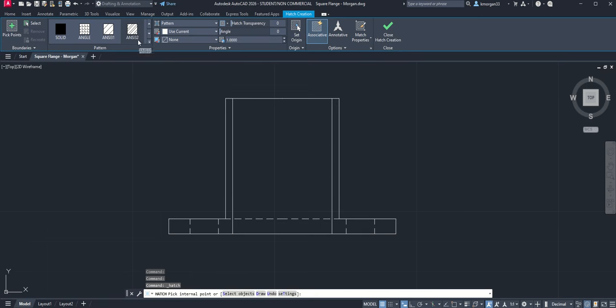The ANSI standard 32 is our pattern, and then we go all the way to here, and instead of 1 we want to make it, in this example, 0.5. That is what you set up for your hatch. So we did this standard, and then we do this, which is this little hatch pattern, and scale it down to half.